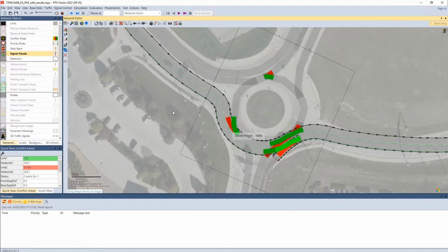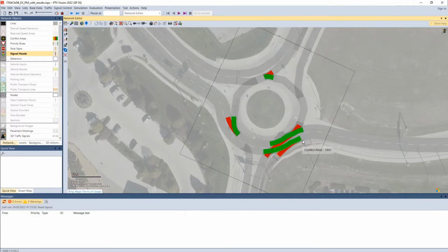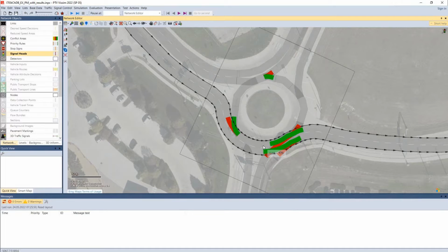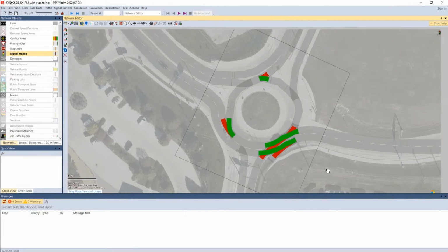Also, with multi-lane roundabouts, it's very common to block lane changes. And since we have a dashed white line, that is allowing lane changes through the roundabout, typically for safety purposes and to reduce as much confusion as possible, designers of roundabouts will prevent lane changes while within the roundabout. And so in this case, you might see a solid white line going through this section.